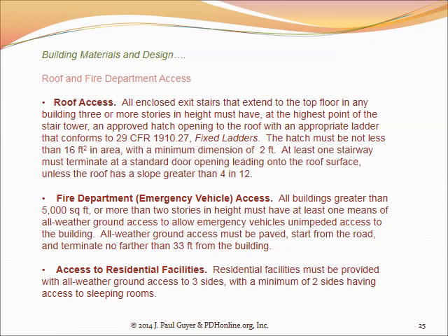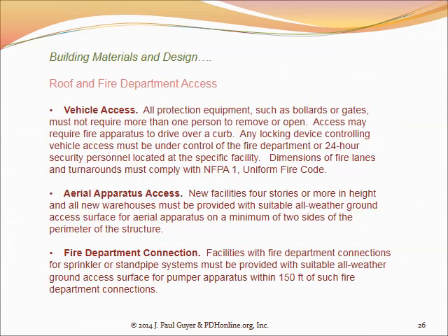And again, this is all mandated by code, and you just have to look it up. In a typical building, again, I'm talking about a multi-story building, you have either a wet pipe or a dry pipe fire riser in the building. And the way things work is on the outside of the building is a connection that connects to this vertical riser, which typically runs vertically in the stairwell.